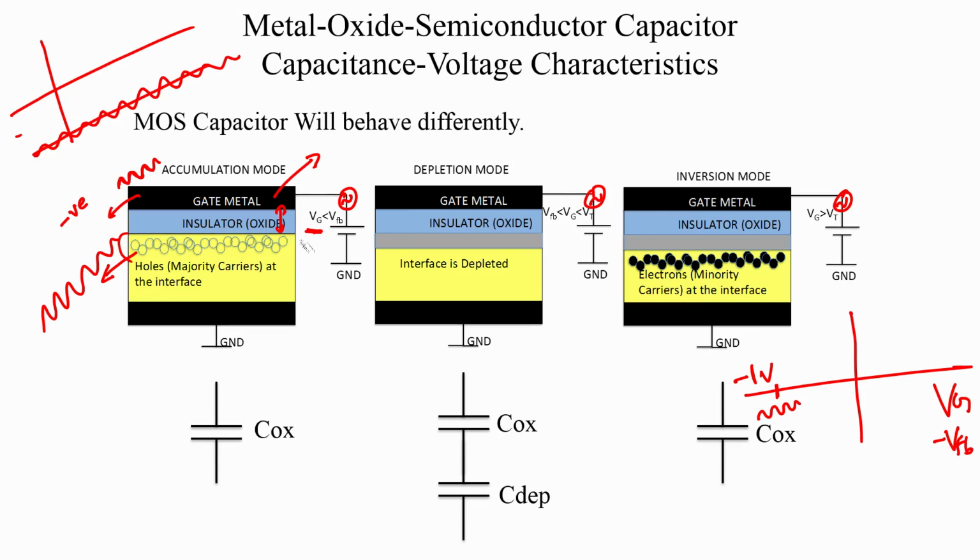But more properly what we are looking at is the charge fluctuation in the device under test in response to the applied signal. And what is the charge response? It is the hole fluctuation in the semiconductor insulator interface. And therefore, our dQ by dV applied, the small signal applied voltage, is simply going to be, what is the fluctuation there? It is simply Cox into Vox, right. So, Cox into V, that is the voltage difference. And therefore, our capacitance is going to end up being just Cox.